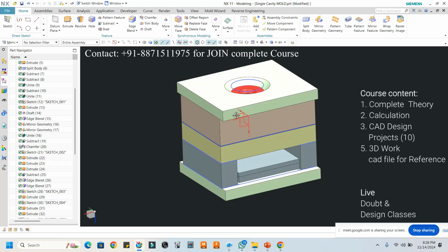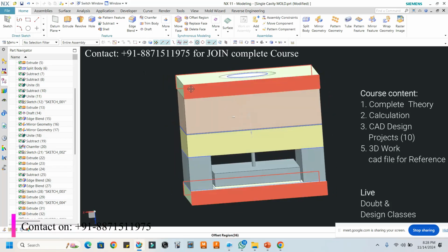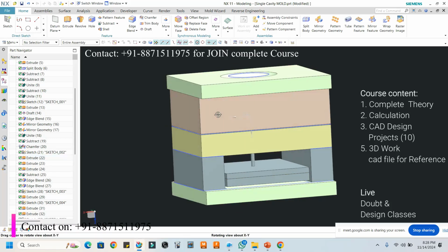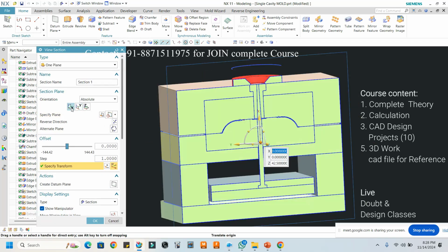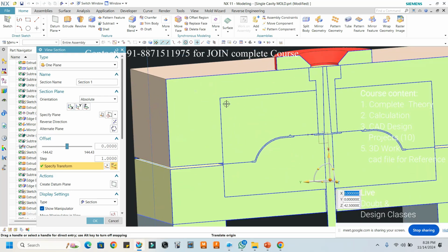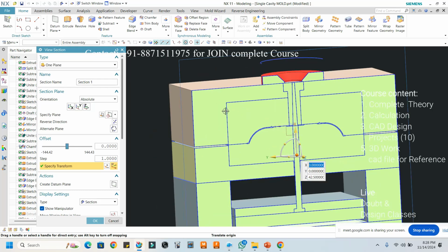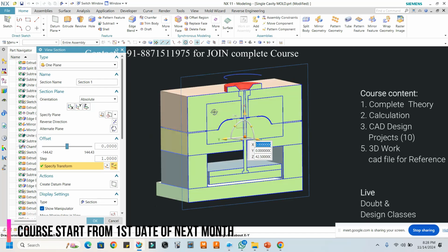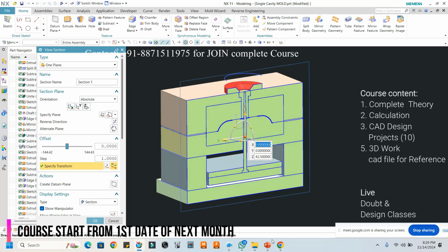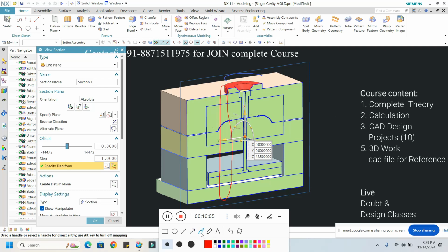For example, first of all, we have to clamp this top plate with the cavity plate, right? And we have to clamp the cavity plate with this insert, right? But with the help of bolting. And apart from the bolting, for the better alignment, what we have to use? Dowels, right? Correct. Dowels are also used in the mold.